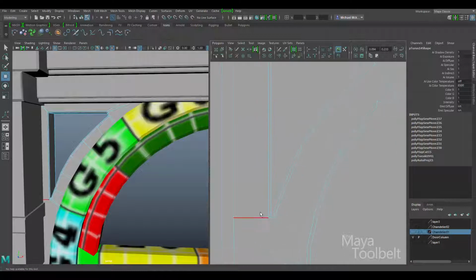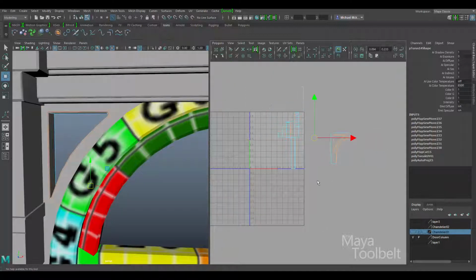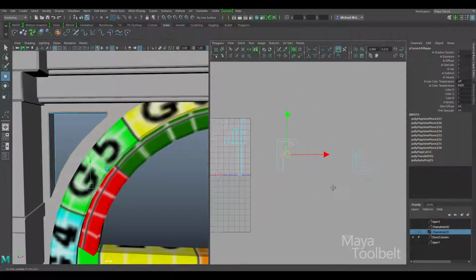Looks like I got them all. So once I have them, I'm actually going to just select them all like this, and then make sure I deselect all of these and all of these. So then I only want these little gaps to all be merged together. So press G to redo the Move and Sew, and it looks like that worked fine.